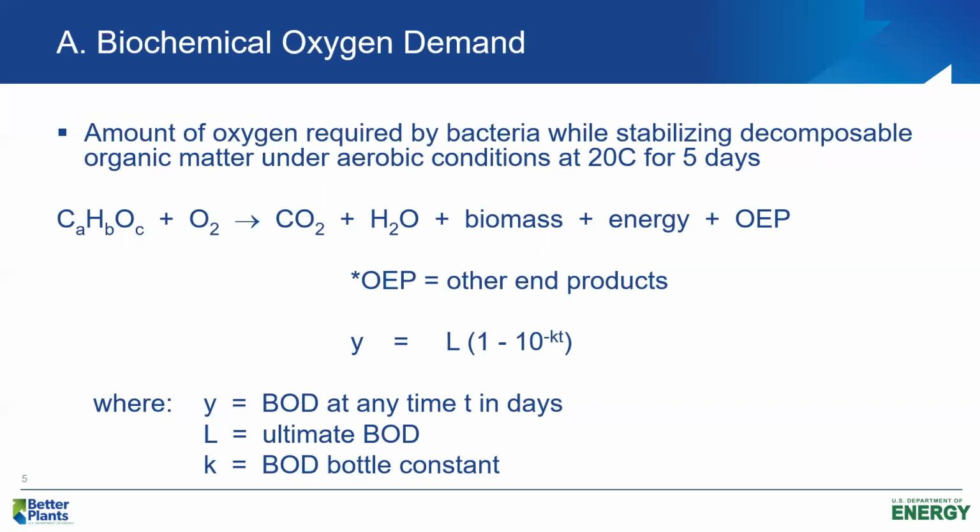So it's actually two reactions in one. We have the synthesis reaction and the energy reaction, or you could call it the growth reaction and the energy reaction, combined into one. But the energy reaction basically is organic matter plus oxygen being converted to CO2 and water and energy. That's the energy reaction. The synthesis or growth reaction is organic matter plus nutrients yields biomass. And the one that consumes oxygen is the energy reaction.